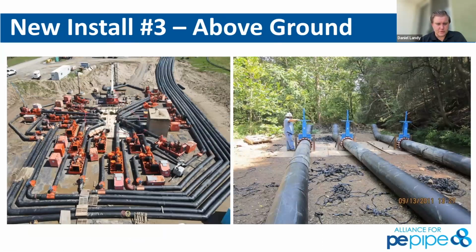And these are just some more examples on the left. I believe that's a temporary bypass job going to all the pump houses, a job in Baltimore, Alan, is that correct? This is similar. This is just showing how complicated temporary bypass for large diameter sewer or transmission mains can actually be. High density polyethylene is one of the most common pipe material types to be used and reused for temporary bypass. It's all above ground and protected by the group when they do that. And if it is damaged during installation, they can just cut that section out and refuse it. So that's why we show it, Dan.